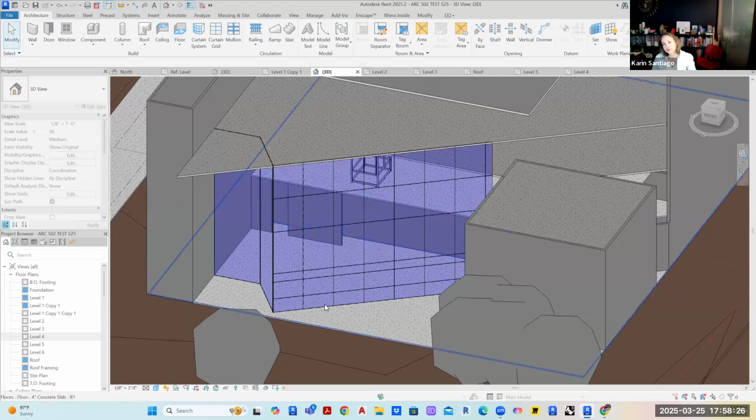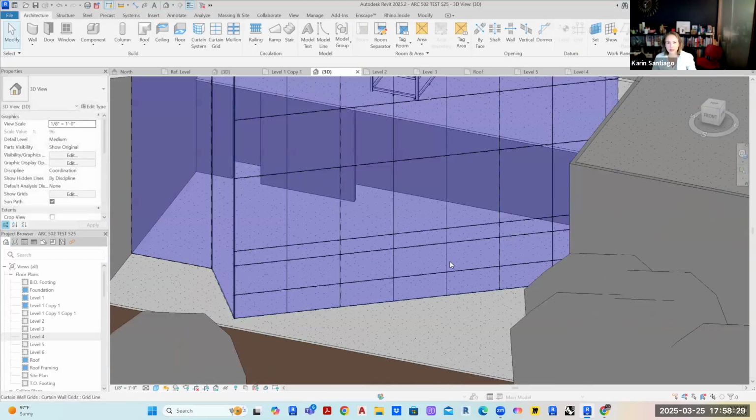And you don't have to always have crisscrossing. You can opt to do only vertical mullions, but your glass has a limitation. Usually a piece of glass can only be as big as an oven where we actually heat the glass and set it. So usually glass, once it starts to get bigger than a 4 foot, 5 foot panel, starts to get very difficult in the width. And then it's probably as tall as 12, 14 feet.